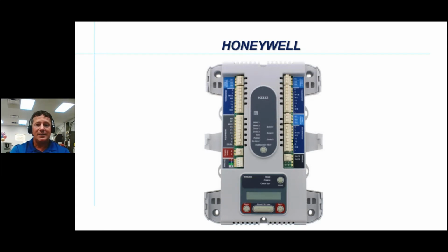If I'm doing a class on a particular item, I want to tear this thing apart. I don't want to see the pretty box. I want to look at its innards, see what it's made out of. I want to go to a wiring diagram, because a wiring diagram is going to show me the capability of any piece of equipment that I'm working on.